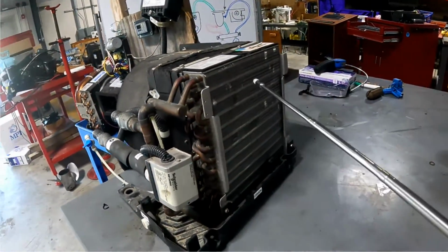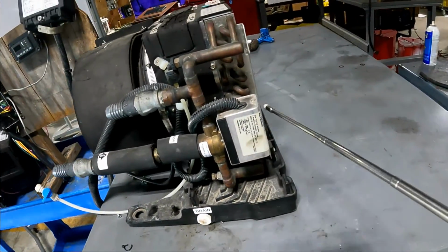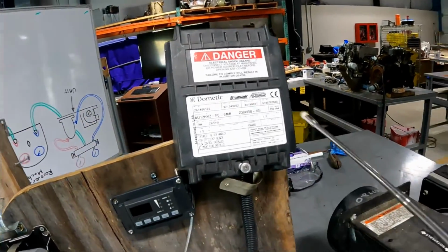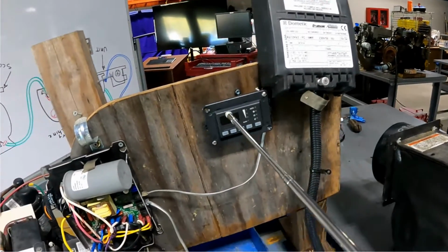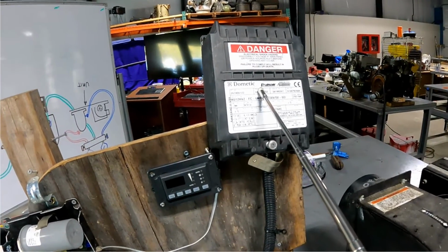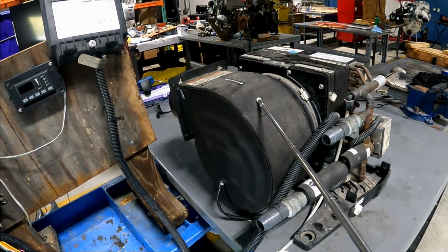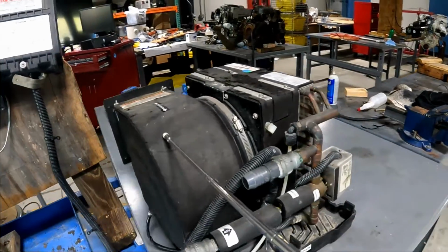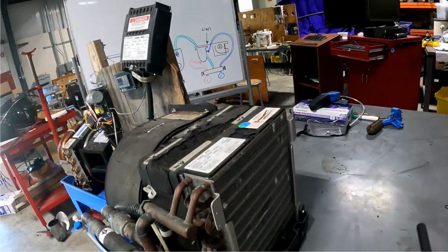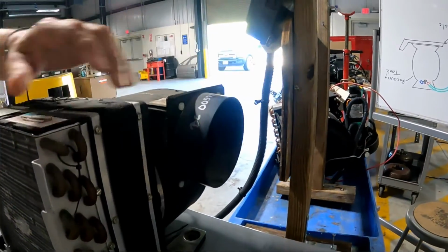for example, for the master room. Okay, the flow of fresh water over there enters in the bottom, the coil, and this is the return of fresh water. And of course, the control box, this handle is activated from the thermostat. When you select the appropriate temperature, the circuit board in the control box sends the signal, and the electric fan, 230 volts, starts and suctions the ambient air from here. The filter is located here, and sends the cold air over there at low temperature.